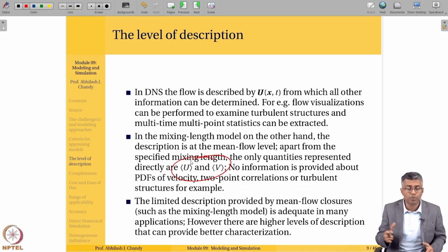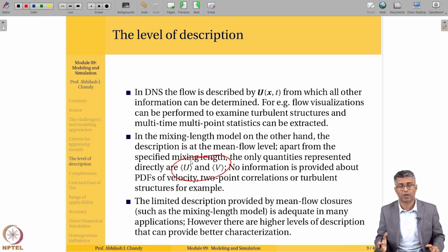Now, even between turbulence models, one can be more accurate than the other. We are not getting into that here. So for the mixing length model, we picked a very extreme RANS based approach. One of the first models that was developed. It's an algebraic turbulence model.